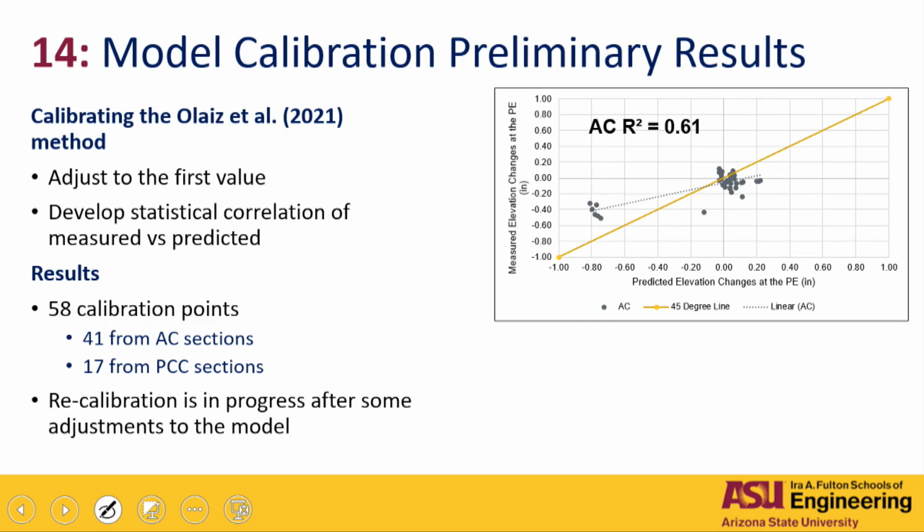All right. Calibration was done for a very small amount of material. This one finished about 2 or 3 years ago. And what is the problem? The problem is we don't have measurements of deflections very frequently on these soils. So we went for data from the Long-Term Pavement Performance program, which is a big database that we have in the United States, and figured out deflection information for places where we know that the soil is expansive, okay?